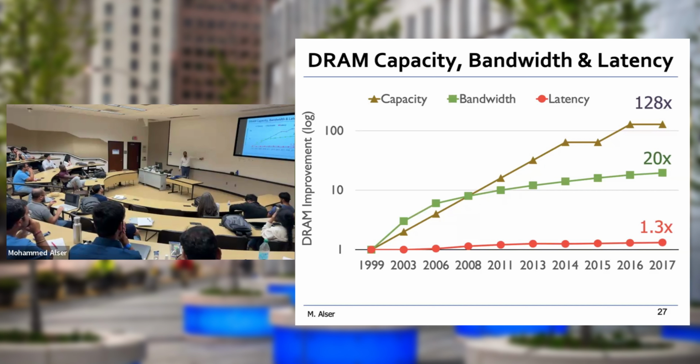So we are limited by the end of the day by only 64 bits. So the latency to send those bits in the interface is almost constant among all of them because they are using one channel and we are accessing the same number of DRAM chip and all of them accessing single location in a bank and give us all those data, okay?